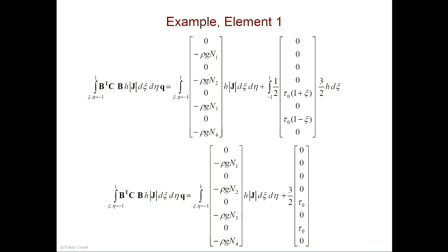What about the channel? Sorry? What about the channel? Triangle. Well, we're just looking at quadrilateral so far. So at the element level, you have a square, or whatever it is. If I do this integral, I think the code is going to put rho g of that element divided by the node. So it would be rho g divided by 4. It also needs to consider the area. So the area of the square is about 9 times the thickness 1. So you can calculate the weight, and it will be putting a fourth of a weight on each node. I think that's what it's going to do. Check it out. Tell me what you find. I'll be interested.